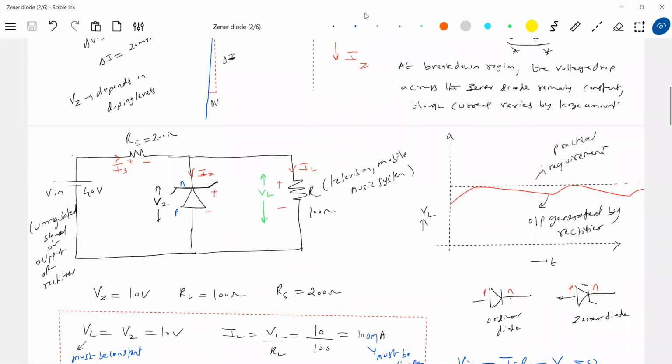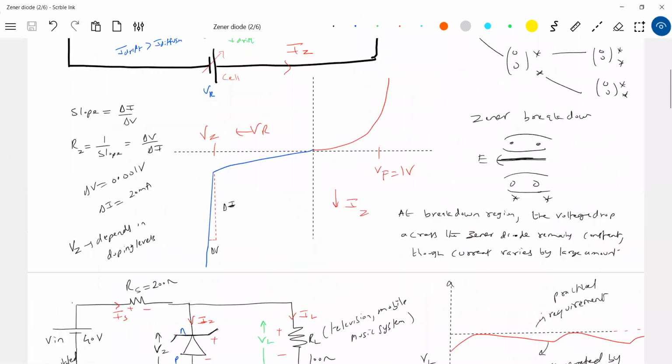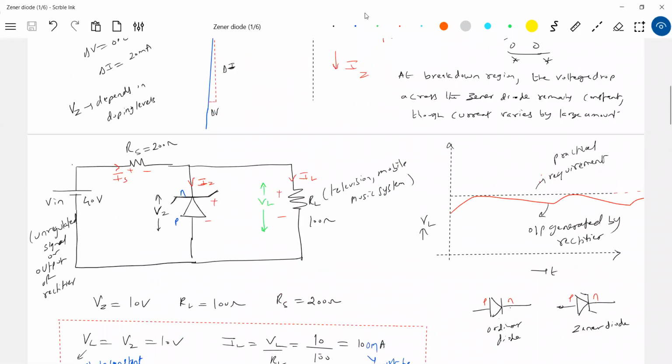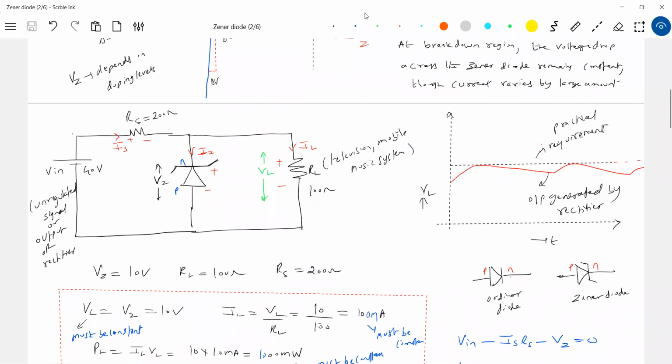Because the 240 volt will not be constant. One more big headache for the half wave rectifier and full wave rectifier. The 240 volt will never be 240 volt. Sometimes it will become 220, sometimes 260, never constant. So this particular thing will always be fluctuating, but we want a constant voltage. Half wave rectifier is unable to do anything, full wave rectifier is helpless.